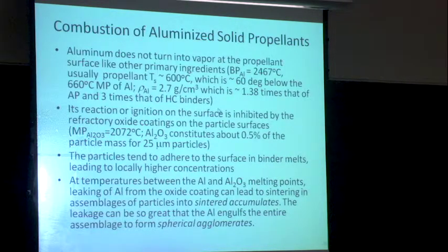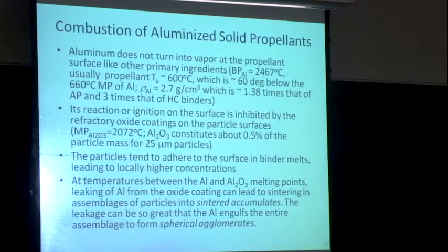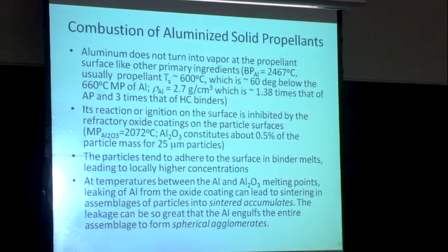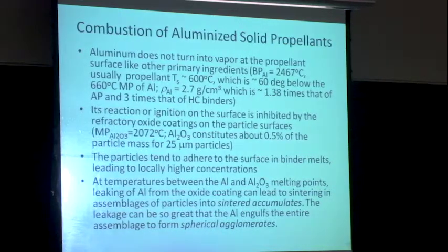I showed you some pictures of how aluminum burns. Typically, the aluminum will rise to the surface. Its melting temperature and its ignition temperatures are typically higher than the surface temperature of propellants. And remember the size distribution. Remember, I showed you the size distribution of aluminum particles was in between the fine size and the medium size. And then I had these very large oxidizer particles.